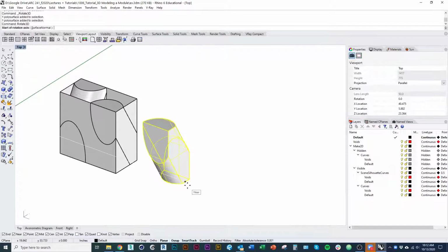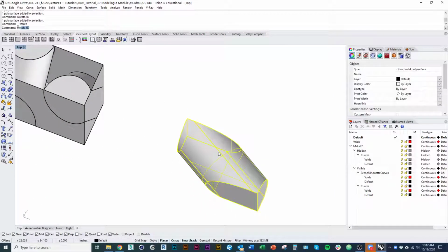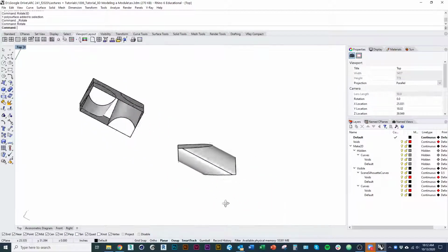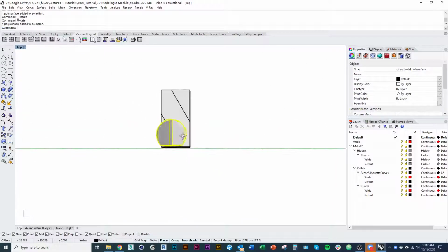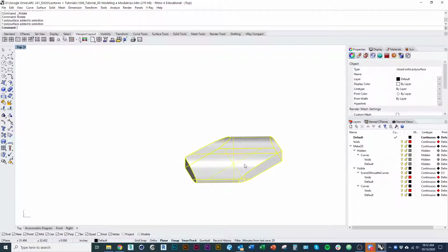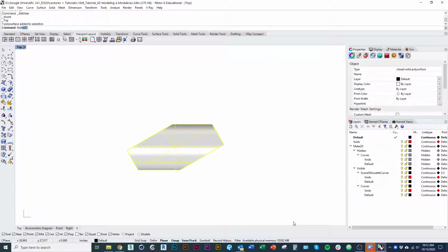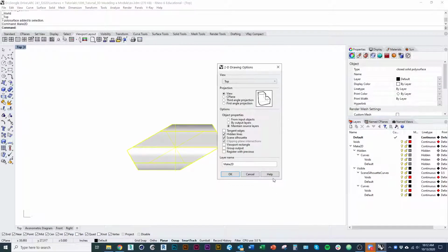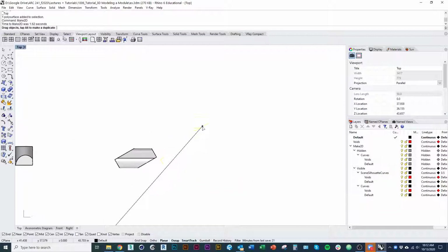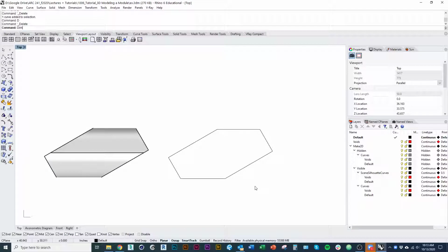I would go rotate 3D and flatten it out first. And then I would also rotate just so that we're straight with the cylinder, because we're going to take all our measurements from that cylinder, right? So one of the things you could do here, if I go to top view, would be to take this shape and go make 2D. There's the shape. And then what I would do is I would dimension this.